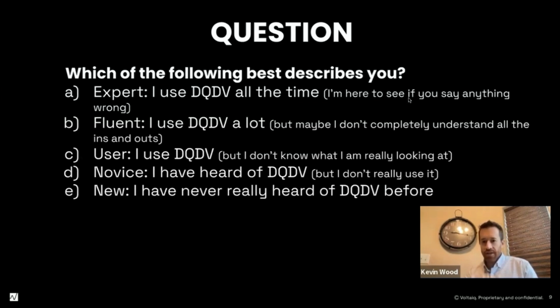Okay, so one of the questions that has popped up is, what's the difference between this in a laboratory setting and the real world? So obviously, when you step on your gas pedal in your car, it's like you're setting a current, right? You're basically stepping on the gas pedal and you're going to apply a specific current. Now, obviously that changes. The way that we do a lot of battery cycling is we basically hold at one constant current. That would be like driving at a consistent speed, basically setting cruise control on your car and driving on a flat track.